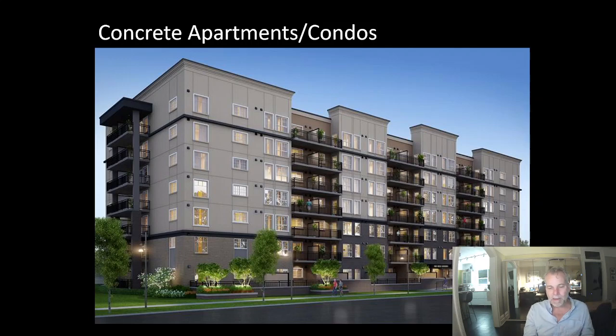The balconies on concrete condominiums are a bit like radiating fins, intended to lose heat. So we have two things that we can do. We can wrap them in insulation, not great from a durability point of view. It's also not cost effective.